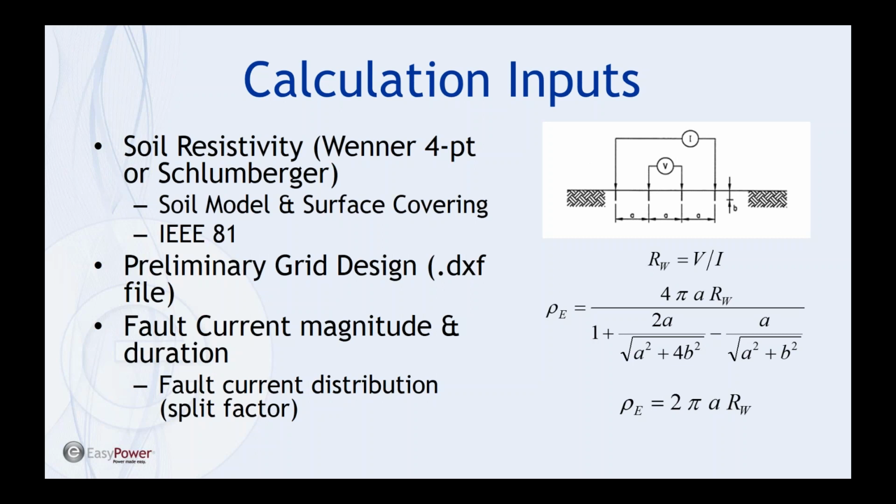Generally, you're not going to need larger than 4-aught unless the fault current exceeds 50 to 60,000 amps, but magnitude, duration, and conductor material all factor into this decision. So it's generally calculated each time depending on what you're using. It's a pretty quick calculation.